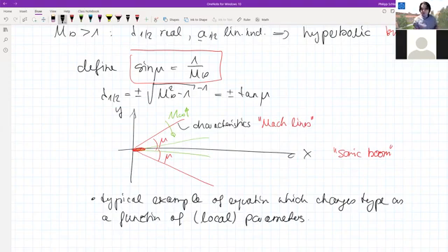Locally it may be so that the Mach number is larger than 1, and then suddenly you have a region where the flow has clearly hyperbolic behavior. And as I was saying, knowing this determines what type of solution methods you would be choosing.